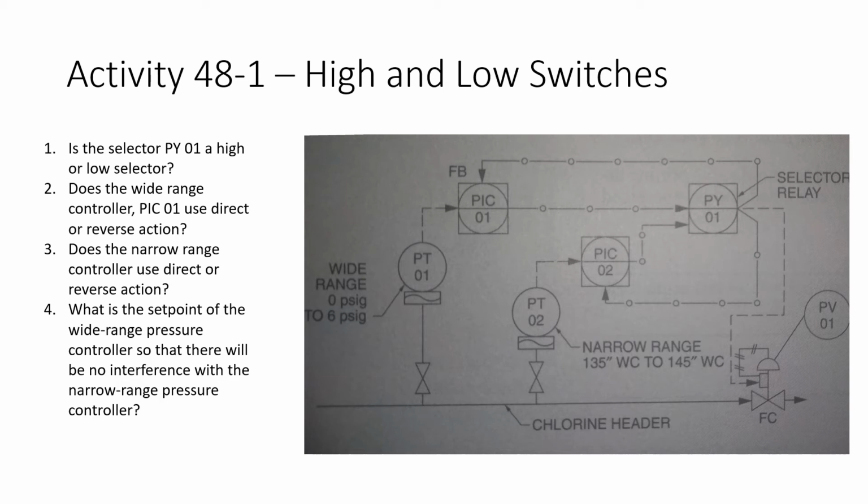And so we have a very narrow range that we want to control this electrolyzer system, this gas generation system, at. So what we need is very tight control here. But if we're bringing it up to pressure, we don't want tight control on that. We want quick control. So we have a wide range for when we're bringing it up to pressure or depressurizing it. We have that for this one and this controller.